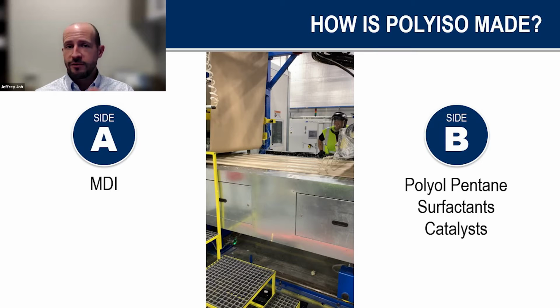So if you need certain approvals, you're putting ISO or some other material, a cover board over a combustible deck, do you need a Class A fire rating? In a lot of cases, you can achieve a Class A fire rating directly over a combustible wood deck, going with a coated glass type face product. So that's another benefit there, allowing you to achieve better fire performance just by switching out the